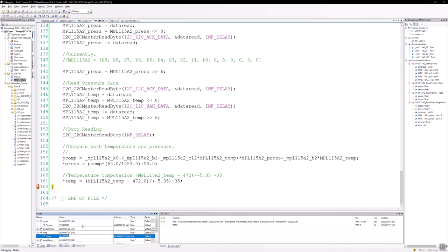The other thing that you have to make sure to do is, besides just hooking it up, there's actually 5 wires, and even when I did this, it didn't work properly, so that's an indication that my sensor's not working, is that you have to make sure to have the shutdown powered up to 3.3 volts as well, because remember that's got to be powered to VDD. So there's actually 5 wires. So I kind of just crammed both of them in there, which is not a good idea. Better thing is to use like a breadboard or split the wires or something like that. But this does show you the code and how to debug it.